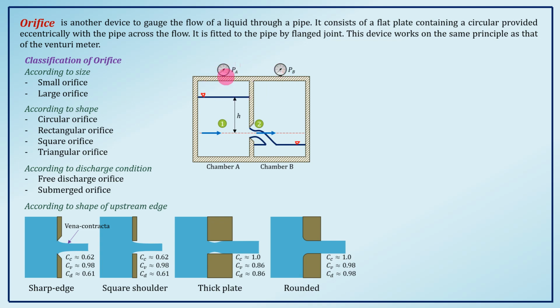This gauge will be used to calculate the pressure of air inside our chambers. Then, selecting 2 points in our chamber, we select a point 1 that lies on our datum, let's say this point. And point 2 is right after the orifice, or where the vena contracta is known. So that is point 2 and point 1.